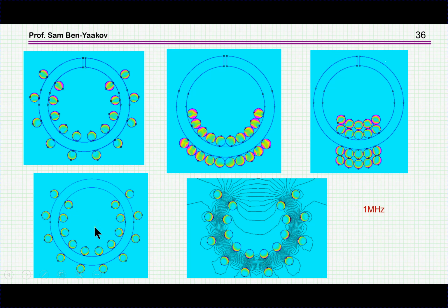In fact, it will be around 100 times lower. So to get the same inductance in the air core, you have to add many more turns, and obviously the total loss will be much higher, although there are no core losses, because you need much more wire in order to obtain the same inductance as in these cases.